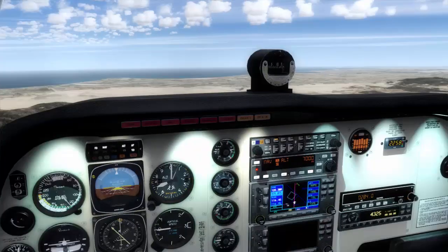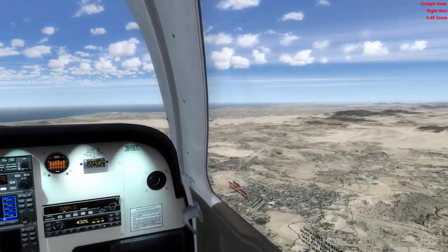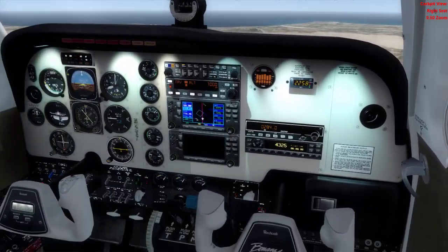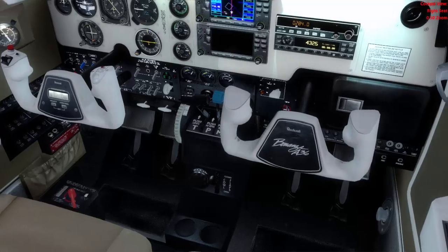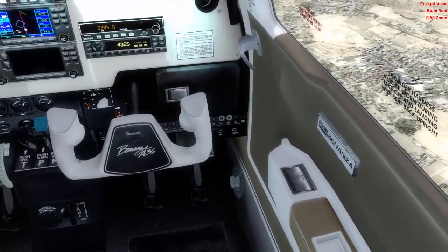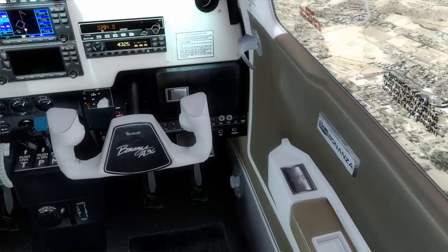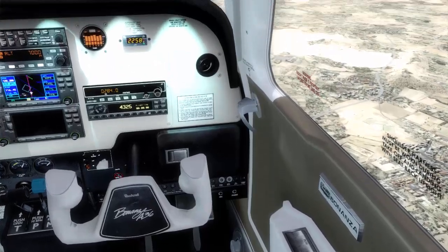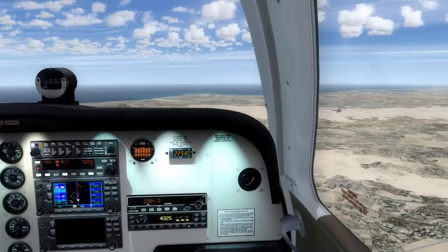So we will have to decide what cruise performance chart to take. If we are having a value of 24 inches of mercury, we will have to use the 25 inches of mercury chart, and it is recommended to fly rich, okay? So we will have to use the rich cruise performance table for 24 inches of mercury. That will be the cruise performance table of 25 inches of mercury, and a rich cruise performance table, okay? 20 degrees rich of peak, or off the peak, okay?